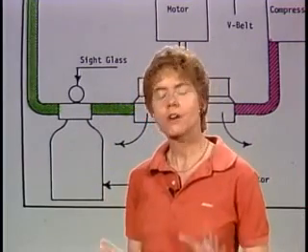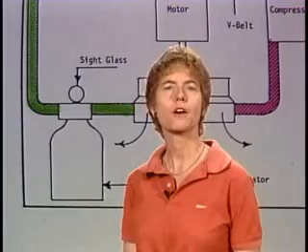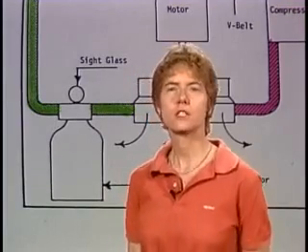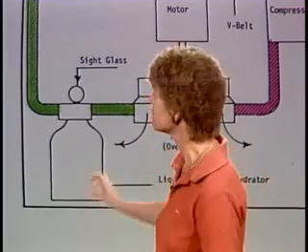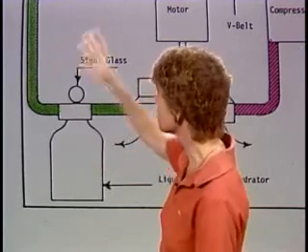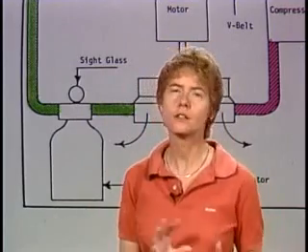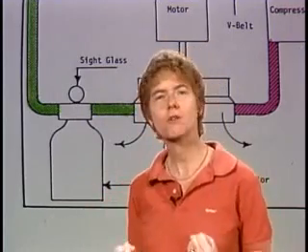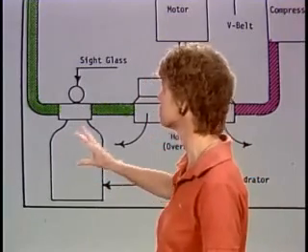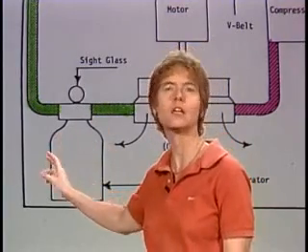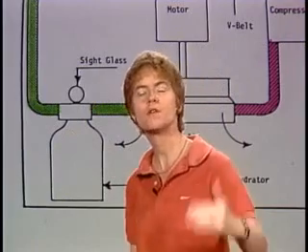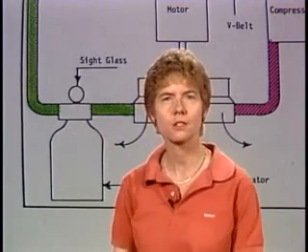If you get water, even a small amount of water, in the vapor cycle cooling system, it can freeze in the receiver and stop the entire operation of the Freon system. So we're going to take precautions when working with a system to avoid getting water in it because it can freeze in the receiver, as well as another place that we're going to talk about.